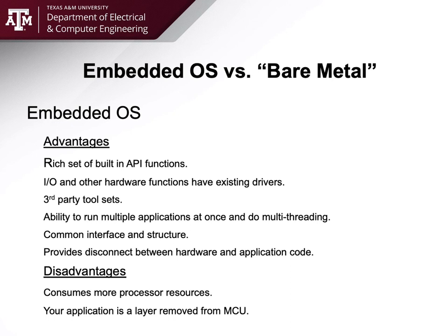So the main advantage of embedded Linux is, if you know Linux, then you already know your embedded system interface. You literally go on the console port. Usually one of your UARTs is your console port, and you go on to TeraTerm or PuTTY or some other serial port interface, Minicom, and you can actually talk to your embedded system as if it was a Linux box, because that's what it is.